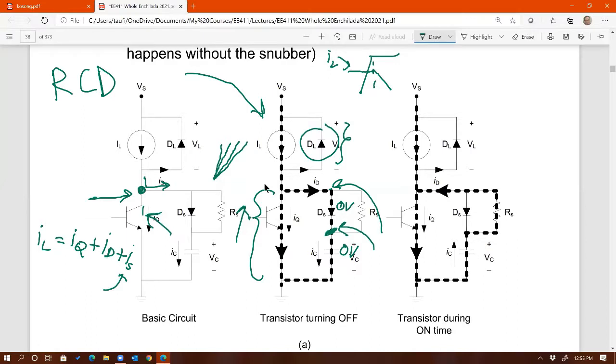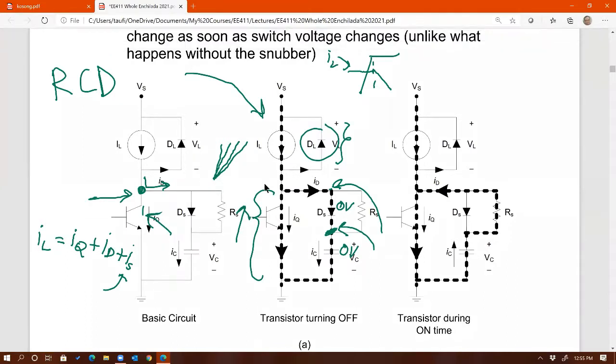Does that make sense first? Yeah, all good. Okay. All right. Again, that is possible because we are allowing current to go through another path, right here. That's another path, so now we're allowing current to charge that cap. Before, there is no path there. You just have a switch, an inductor, and a diode. But now we do.